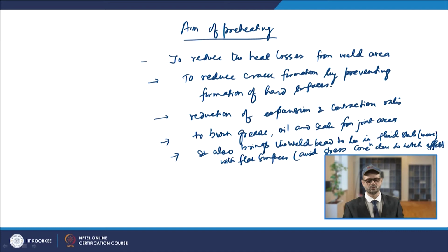So, that is another reason preheating is given. Also, when the liquid metal is there for a longer time, you are giving more time for the gases which are dissolved in the weld pool to come out. So, that is another advantage of this preheating method. They will be coming out from the weld and HAZ.